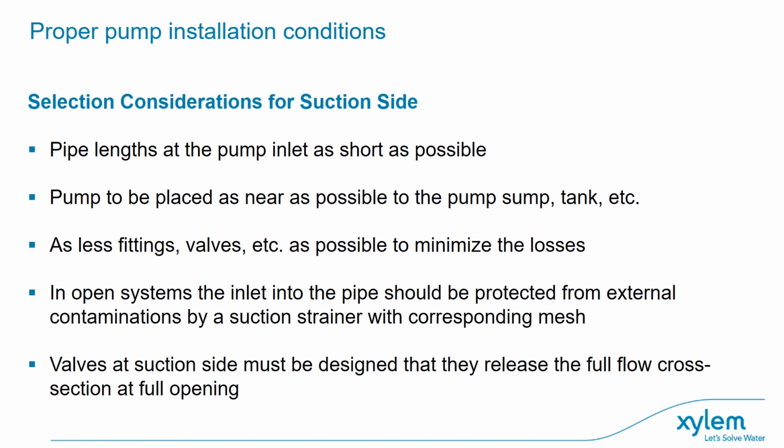Air pockets are a risk for the mechanical seal area. That's the reason why some air might rest in the higher points of the system and reduce the free space for the flow, causing additional losses and reducing the pump flow.